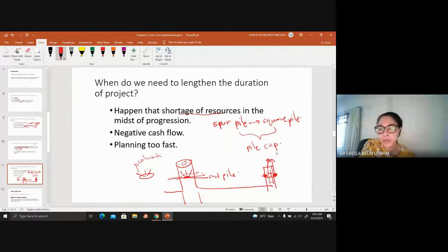Sometimes during the driving of the pile, it will break easily at the top, and sometimes if your pile is not driven straight, it will just break. The strength differs very much, hence square pile is troublesome.